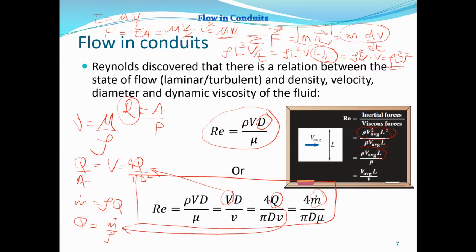So this is a simple derivation of the Reynolds number. By and large, the Reynolds number is one of what we call pi groups, or dimensionless numbers. You can see it's a ratio of forces, so it has no unit, so it is dimensionless. By definition, it is simply the ratio of inertial forces to the viscous forces.